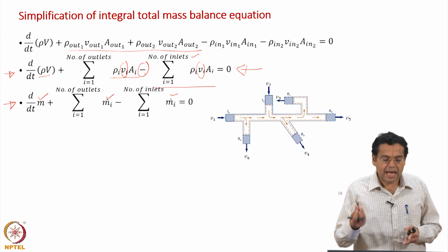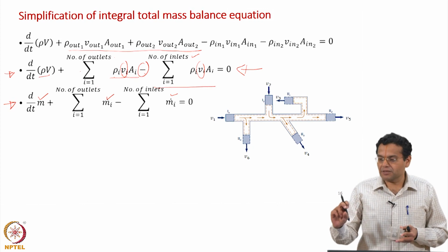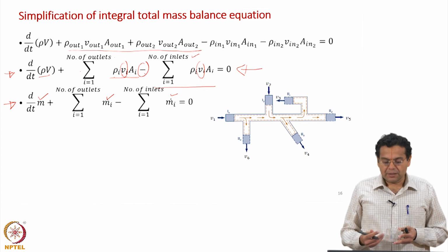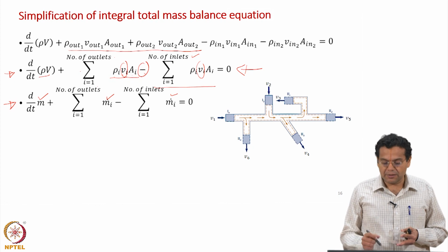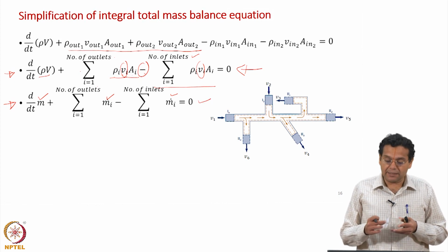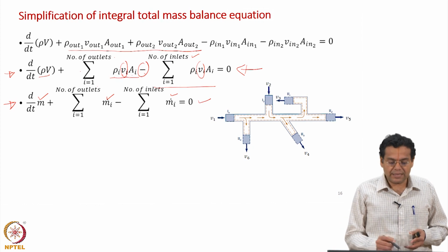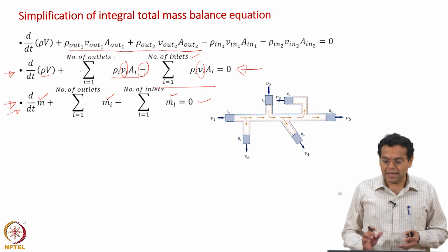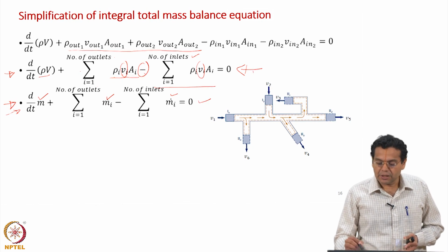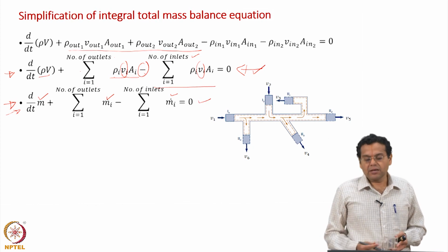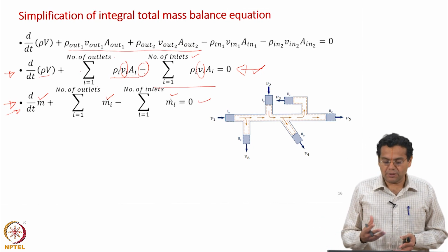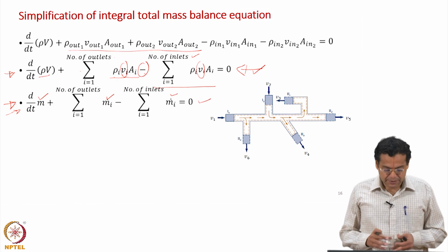And in a lab experiment you may measure the mass of a sample. So, in those cases mass becomes a more measurable value, and some instruments can give directly the mass flow rate itself. In those cases this equation becomes much more useful, but otherwise this is a more useful and general form of the conservation equation in terms of rho, the control volume, velocity, area, etc. Okay.